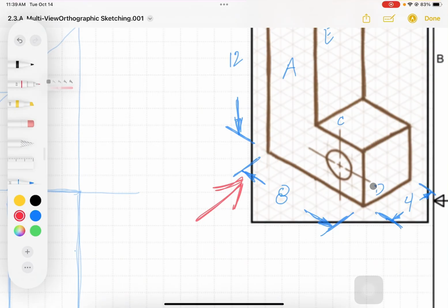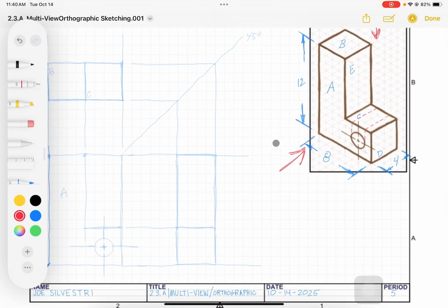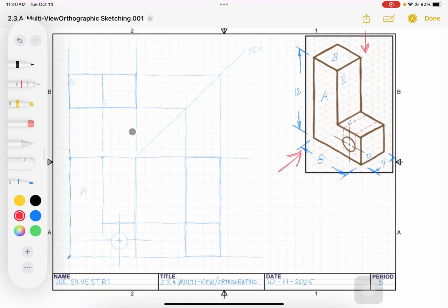Okay, well that looks like this. I want to see the leftmost edge and the rightmost edge. Now what I'm drawing is a dashed line called a hidden line. It communicates to people that read the blueprints that there is something underneath or behind a surface that's in your line of sight but hidden to you. It's a series of dashes. It's showing something that's hidden about the object. Therefore, they have to start, look at my cursor, and end on an object line so that you're communicating that line properly. Okay, so how do I find that up here in the top view?